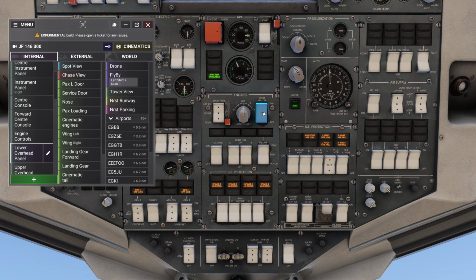Okay, we'll start master 1. I will set the engine, I will start first engine 4. And then do I have to push a button then? Exactly, that's correct. So once you have the engine start master on and you select engine 4, you'll press the start switch for about 1 second, then just monitor the N2, the EGT, and all the relevant parameters as it spools up. Once it's stable, we'll move on to the next engine.